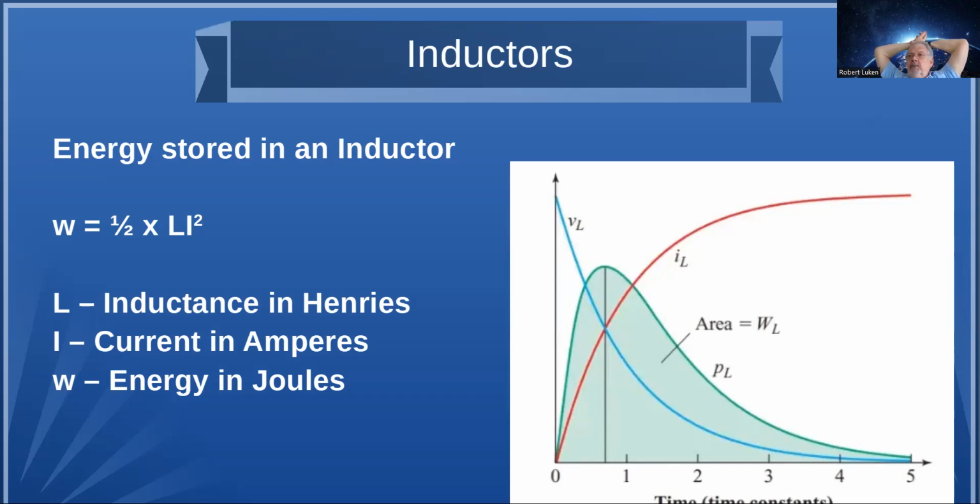So whatever voltage we apply to it initially is what the voltage across the inductor is going to be. The current, therefore, is going to start off at 0, where in the capacitor, the current started at whatever the maximum was, limited by that series resistor.